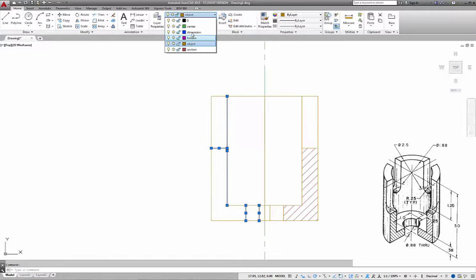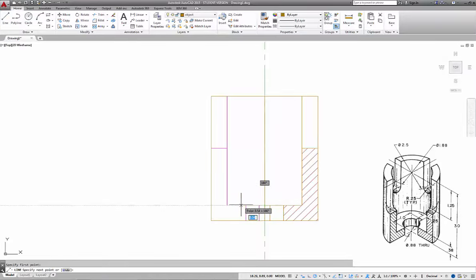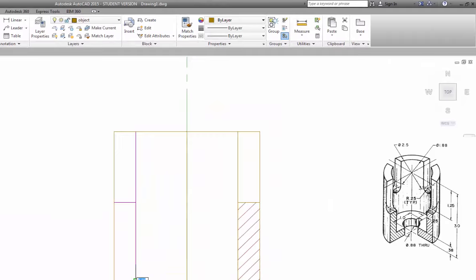We have to make additional, we forgot to do that. But notice that if we make this line a hidden line, it's going to select everything. So what we're going to do is move this back to the center, and redraw another segment just so this one can become a hidden line. Because again, we want to make sure that hidden lines are on the left-hand side only.